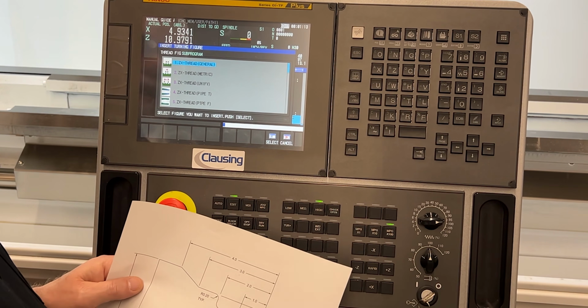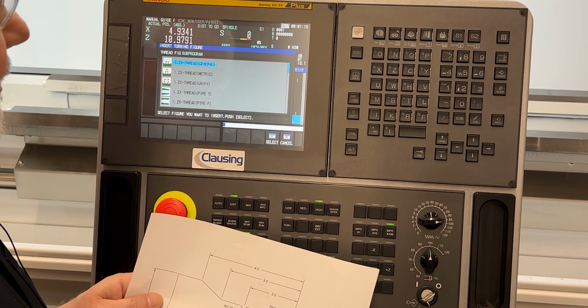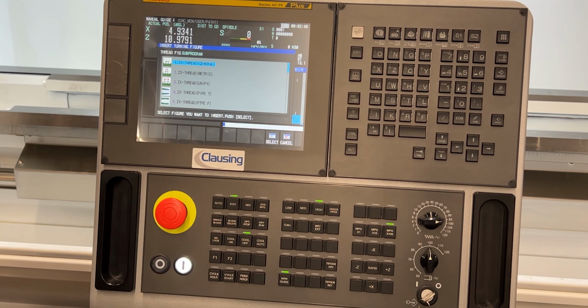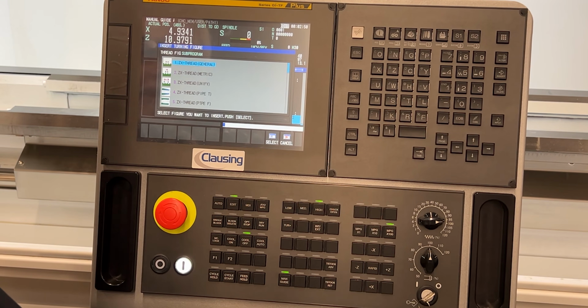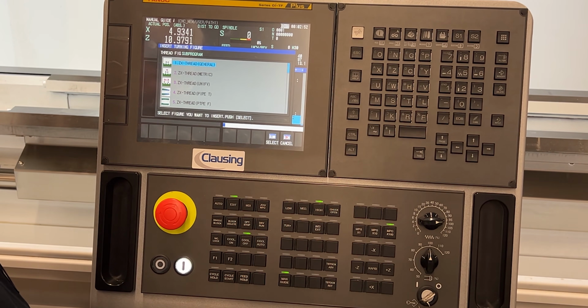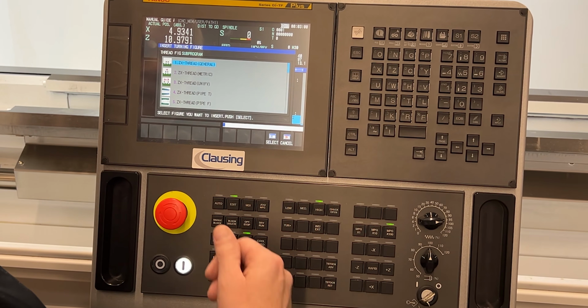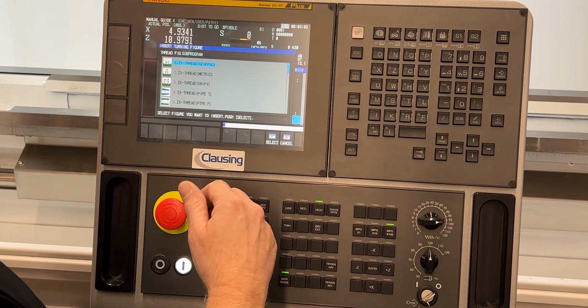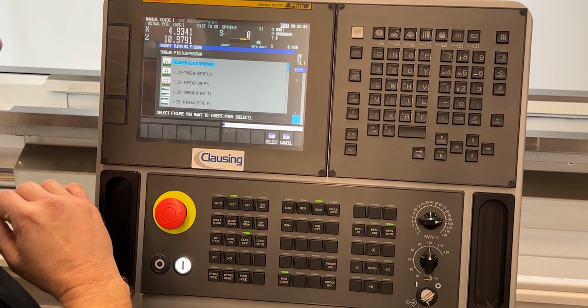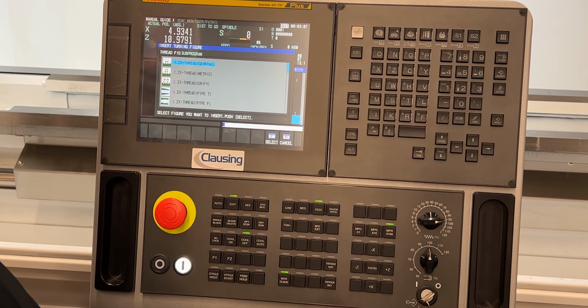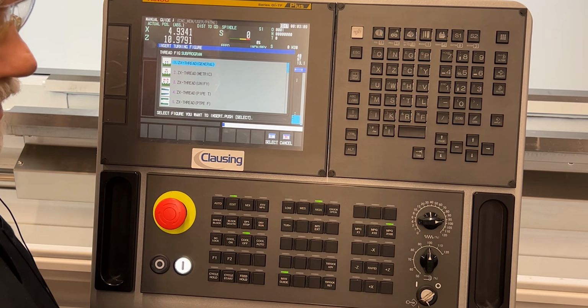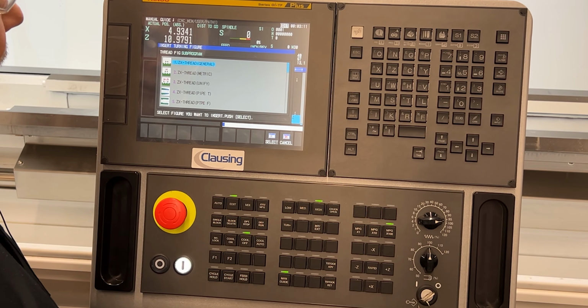And again, a figure will come up that we have to fill in the blanks. Like I said, the thread figure will then pop up after you get the roughing information in there, of what the shape of the thread is going to be and what type of thread. So we have a selection in here. We got thread general, which is any thread that you create out of your mind, or just any type of thread that is given to you.